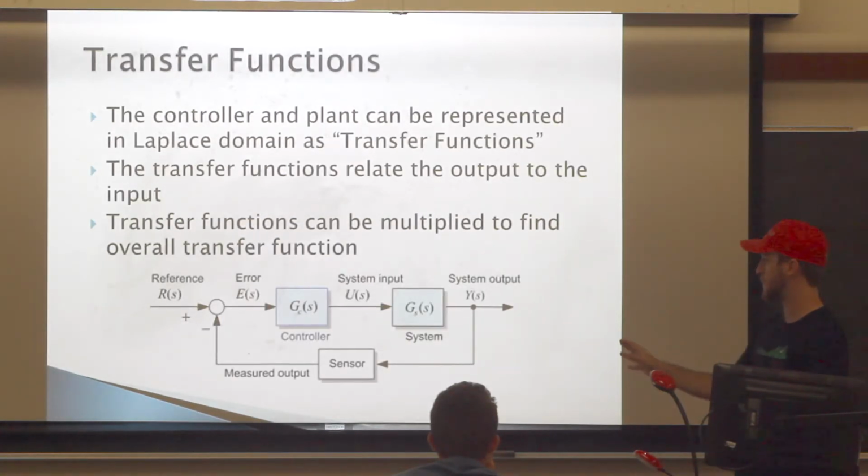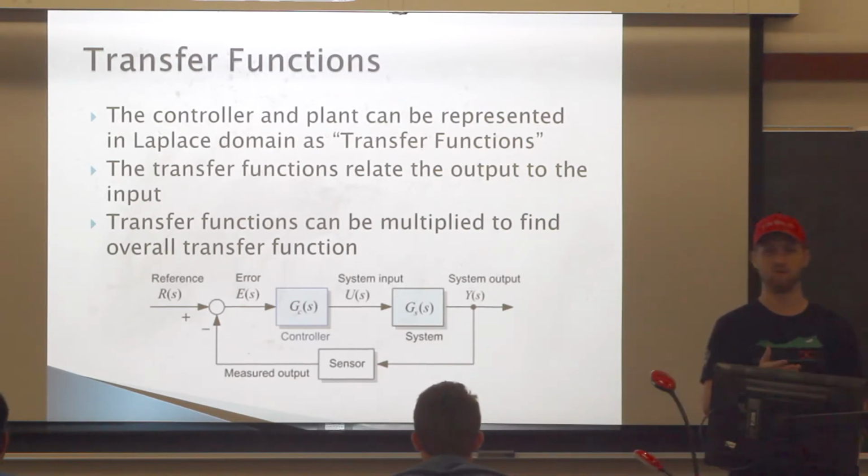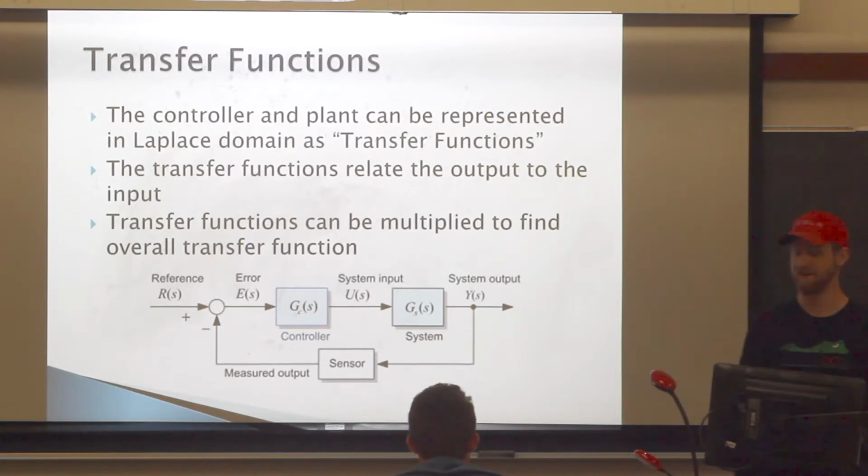Now, transfer functions, I'm just going to cover briefly. Essentially, your controller and plant can be represented with functions, and in the Laplace domain, if you're familiar with that. If you're not, I'm not going to explain it. In the Laplace domain, they're transfer functions, and you can then multiply these to find an overall transfer function. The transfer function relates your input to your output, so you can see how the system works.